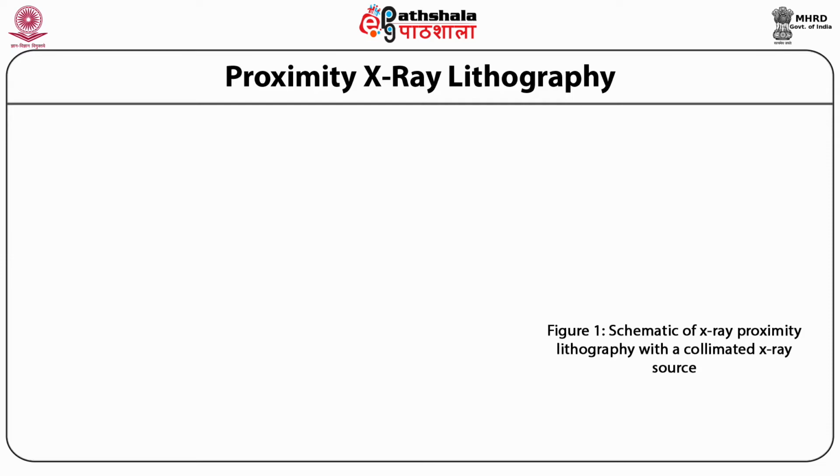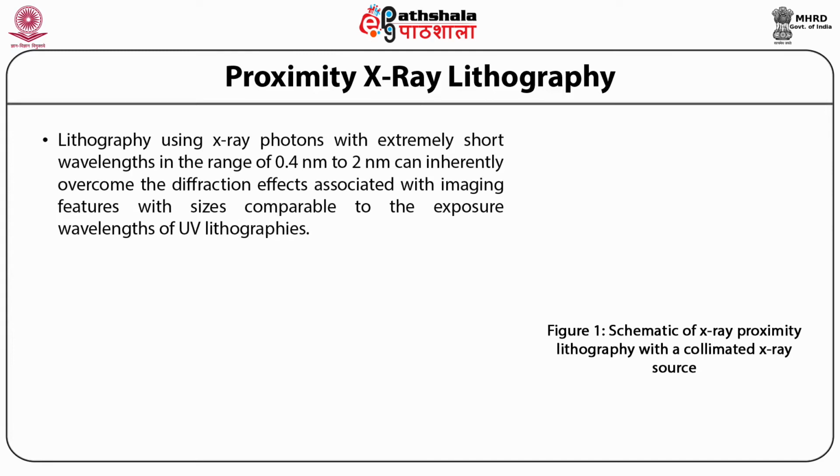Proximity X-ray lithography. The principle behind X-ray lithography is to use X-ray photons, which have extremely short wavelengths in the range of 0.4 nanometer to 2 nanometers. This provides the advantage of preventing the diffraction effects associated with imaging features with sizes comparable to the exposure wavelengths of UV lithographies.